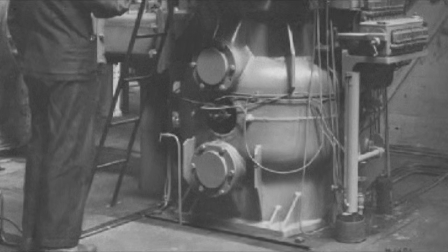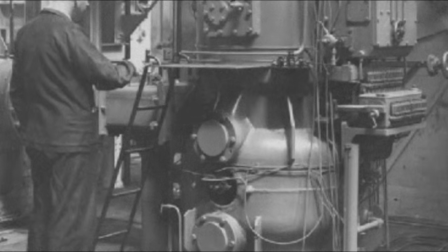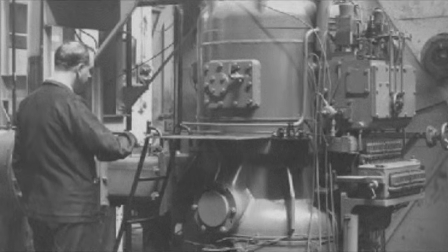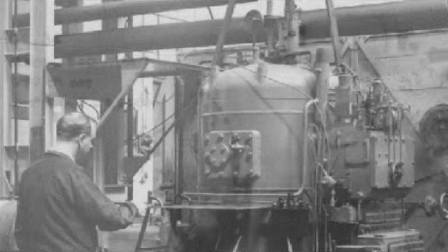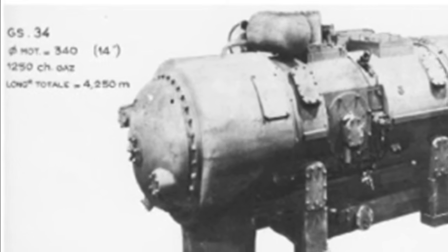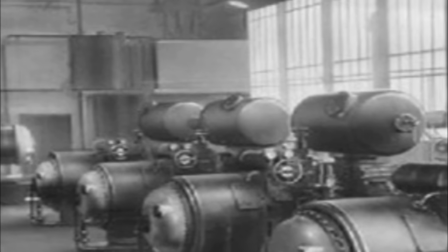The attractive economics and design advantages of free-piston gas generators led many companies in the 1940s and 1950s to turn to this technology and build units that were successfully used in marine and industrial power plants and, with limited success, in large-scale transport. In 1945, the French company Sigma, using Pescara patents, built the Sigma GS-34 free-piston gas generator with a capacity of over 1,000 horsepower, 745.7 kilowatts, for powering gas turbines and stationary power plants. This was the most successful free-piston gas generator in history.